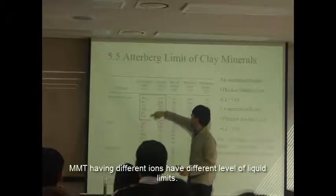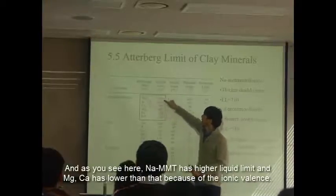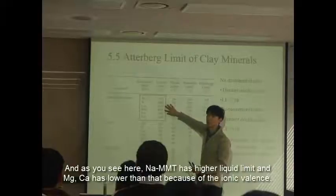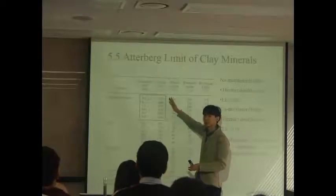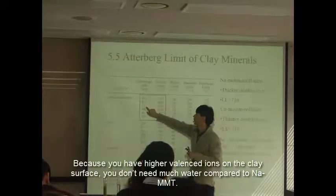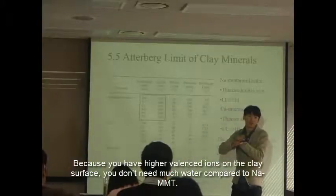potassium and calcium, they all show different liquid limits. And when you see here, sodium montmorillonite shows the highest liquid limit, 710, and magnesium and calcium have lower values than that. What's the reason for that? Because of ion valence. Yeah. So because you have a 2 plus cation on the clay surface, you don't need much water. You need less water than for sodium montmorillonite.